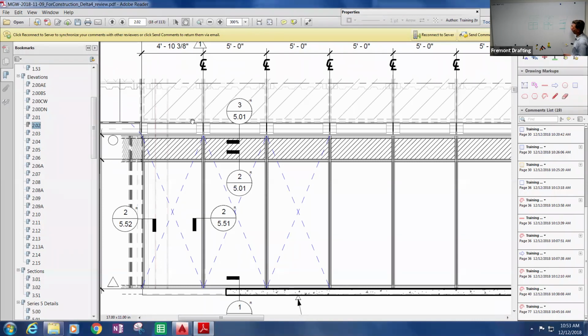Other things can rack and or translate depending on how they do it. So where we run into issues is when I've got this translating element right here, right next to something that's racking. So as I'm on this side and it racks, because I'm attached, that translating element's attached typically at the floor too. It moves over, I've just got a big joint right here.